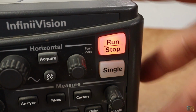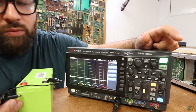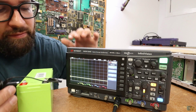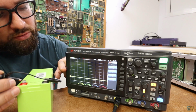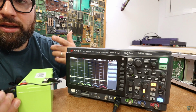Another thing that I wanted to show you is the stop run button and the single one. And this is related with the trigger button, the trigger settings. If you leave it on run, which is right now on green, then anytime that your settings for the trigger are accomplished, it will trigger the event and it will stop the image. As you can see, if I click it here at the same frequency, it will stop the picture on the screen. Basically, it will show me the signal anytime this trigger will happen.